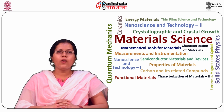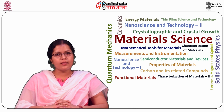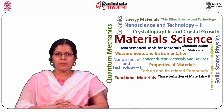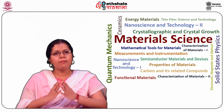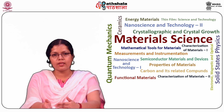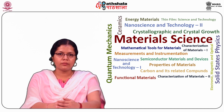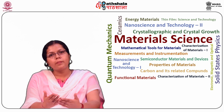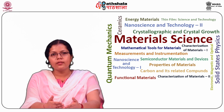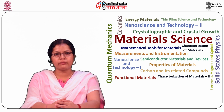So students, now let us study about the Meggers. The Megger is an instrument used for the measurement of high resistance and insulation resistance. Essentially, the Megger insulation tester consists of a hand-driven DC generator and a direct reading ohmmeter. It consists of permanent magnets which provide the field for both the generator and the ohmmeter.